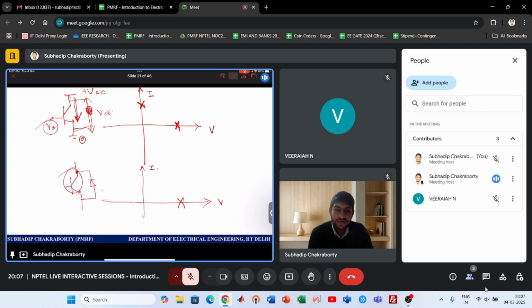The diode will conduct, that is a different thing, but the device will be damaged. So voltage always needs to be applied positive here, not negative. Otherwise, the device will break down. This device will not perform correctly. But the current can be in both directions due to the diode. When the device is on, the current can be in both directions, forward and reverse, both.